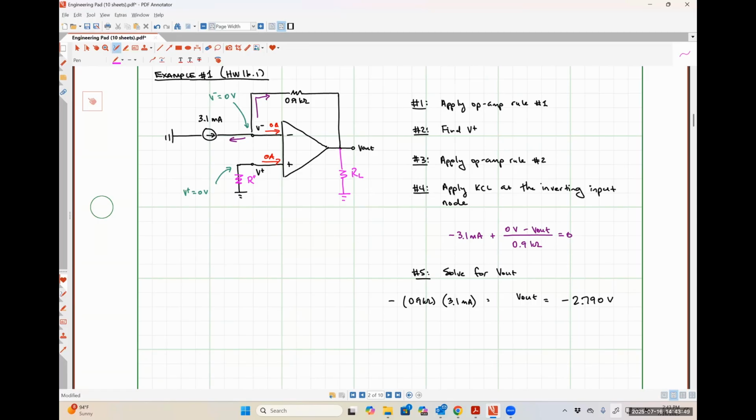From a practical perspective, it's going to try to negate what are called input offset currents, which are going to be incredibly small. So you would only ever do this for very, very high precision amplification of a sensor or something like that. So most of us will never see this, but every now and then it is actually useful to physically put some resistor in series with the input terminal. But from an analysis perspective, again, it's not going to impact anything.